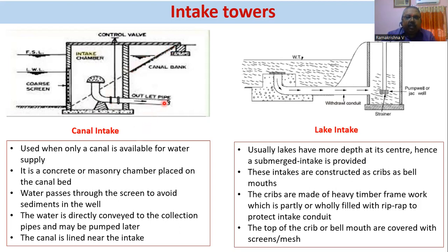So this is a lake intake. Lake intake is also similar to what you have in canal intake. Usually lakes have more depth at the center, hence a submerged intake is provided. So this is a submerged intake. Now you are having a cushion at the bottom of the lake bed, and then you are providing a pipe here, and this is fitted with the bell mouth here. Bell mouth means the shape of the inlet here.